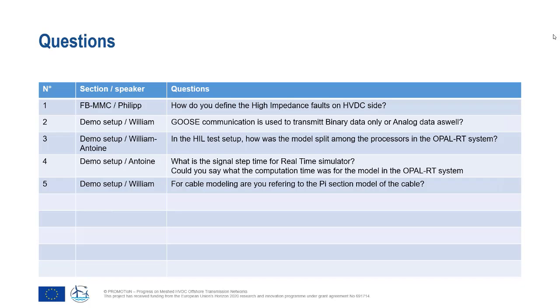But you can always find the type of data that you find in every informatic application. So yes, the answer is not only binary data. With GOOSE, you can also use other types of data. GOOSE is a protocol that is meant to be used for states or for specific events that are not synchronous in time. So, sporadic events.